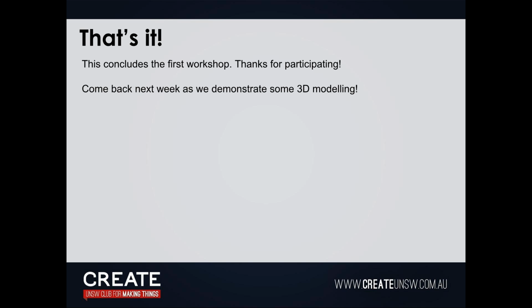Create sketch. You can sketch on that surface. What we'll be doing is making 2 cutouts here. Actually, I'm just going to go with a line, roughly about there. Don't worry about going over, we can always trim those.